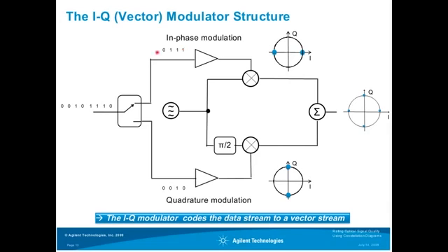data stream, that is, the divided one from the original data stream. At the beginning, you typically have an amplifier on both paths, and then you go to the modulator that modulates your carrier. Here you can see the carrier. The carrier is fed to both modulators, but on one part of the transmitter, the carrier is phase shifted by 90 degrees.